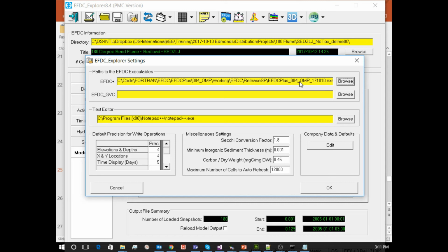Now, what I was going to show is that I'm using a single precision model. If you want to improve that, you need to use double precision. You don't need double precision for many applications, but there are a lot of applications out there where I have found that I needed double precision accuracy to get the answers that I want, because if your system is large and the processes are slow, you get round off.